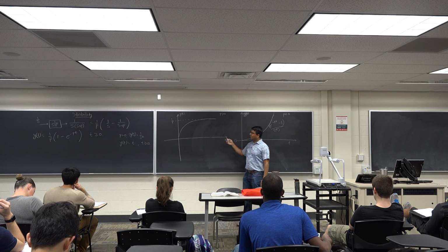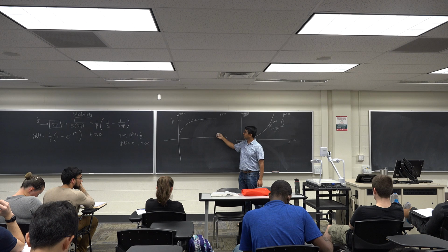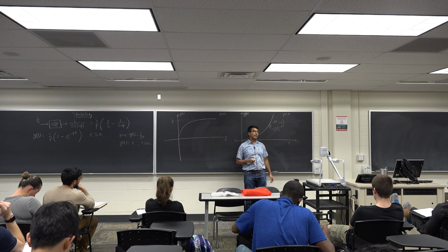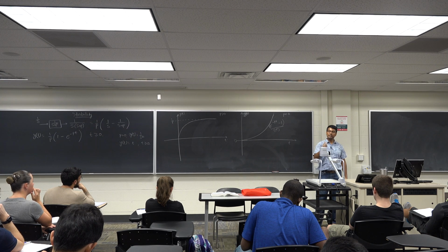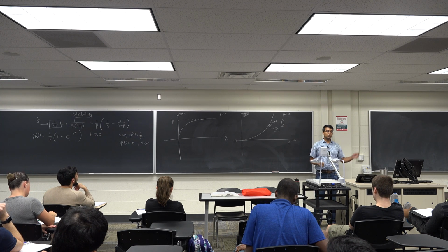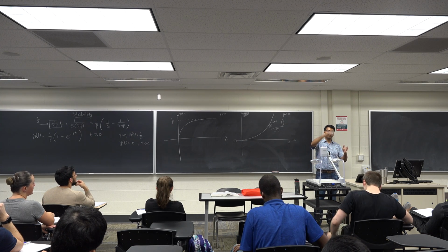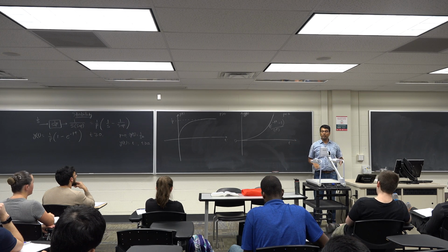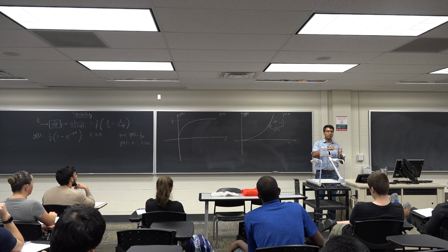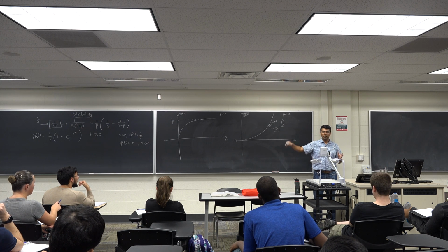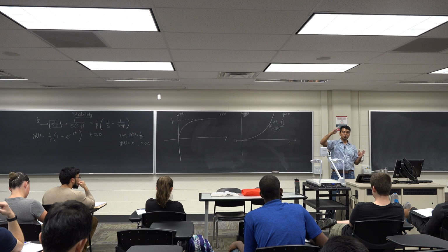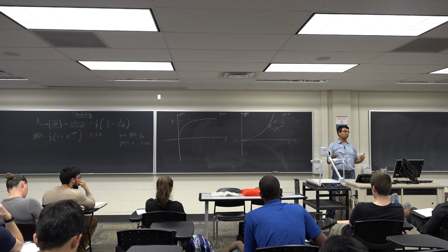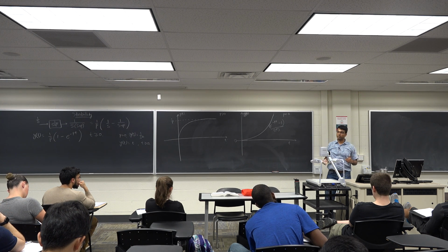So now, in many cases, for instance, in the case of an LC circuit, not an RLC circuit, just LC, we saw that if you give it an impulse input it goes through oscillations. If you give it a step input, it goes through oscillations again, but it doesn't blow up. It just goes through oscillation. Those are known as marginally stable systems.